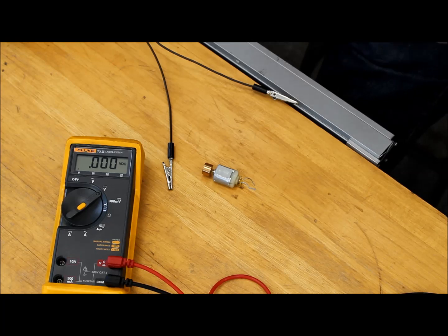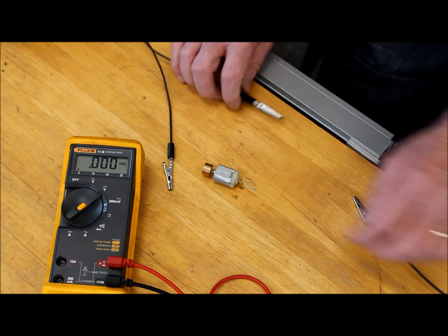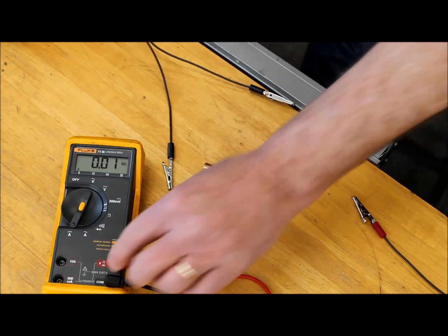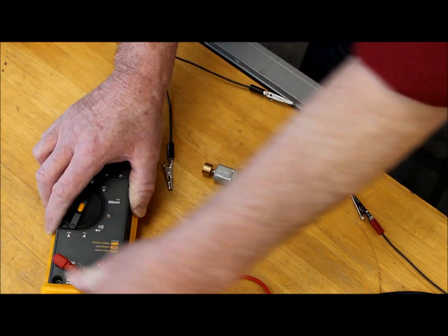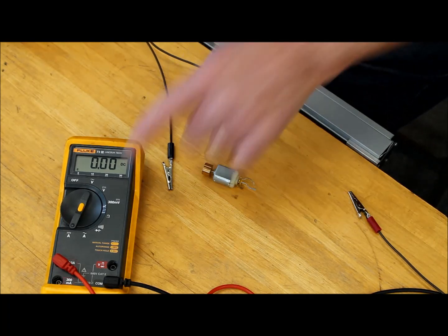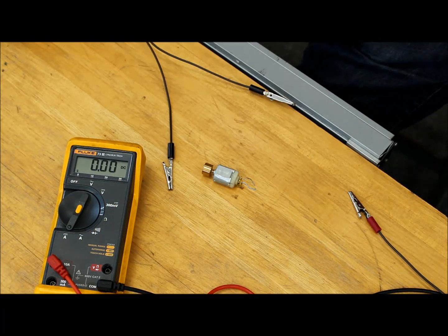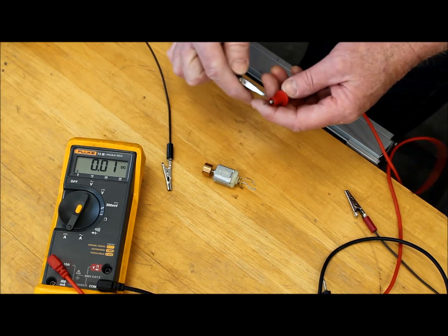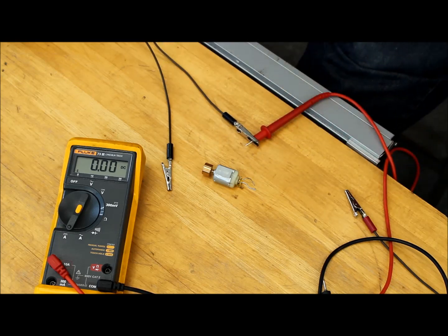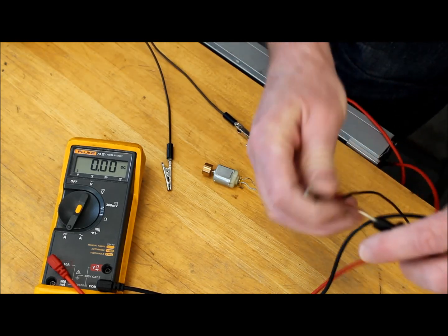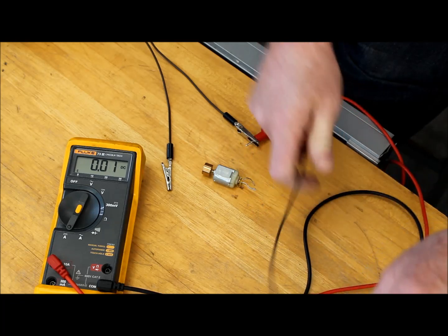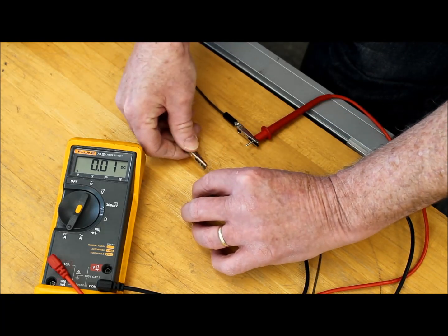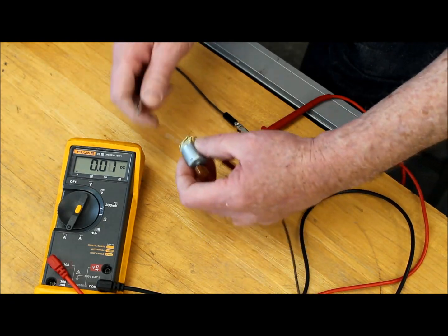And what I'm going to do is I'm going to hook this up. So you notice I have the meter here. I'm going to set the meter on DC amps, and of course we put the leads in the 10 amp spot right here, and then I'm going to run my power from my little power supply through this meter and into this little electric motor, and then from the motor back to ground. And well, let me turn this off a second.